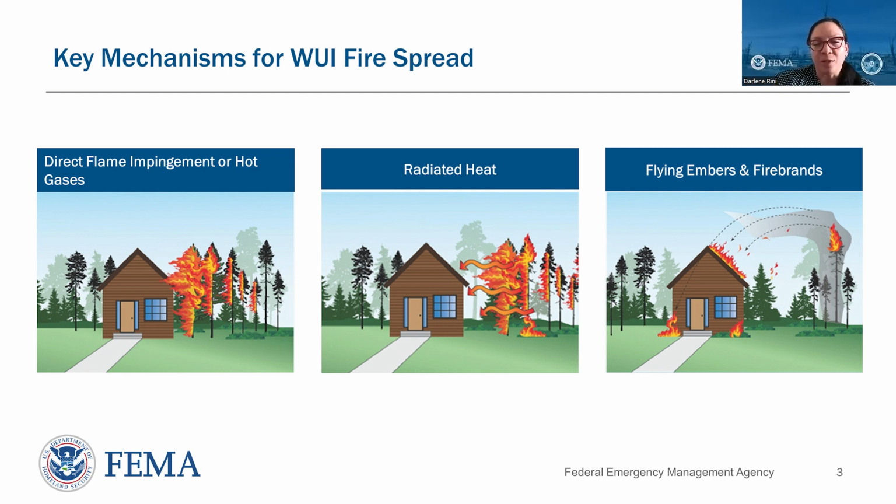And so the main goals then boil down to 1, limiting the ability of a fire to spread uninterrupted from adjacent wildlands and/or open spaces directly to the home or structure, whether via direct flame, hot gases, or radiation. And then 2, limit the likelihood of embers igniting receptive fuel beds and other combustible items within a property that then leads to structure ignition.